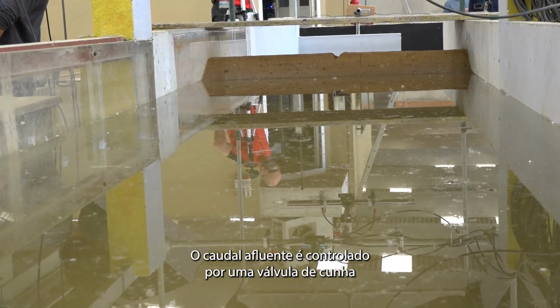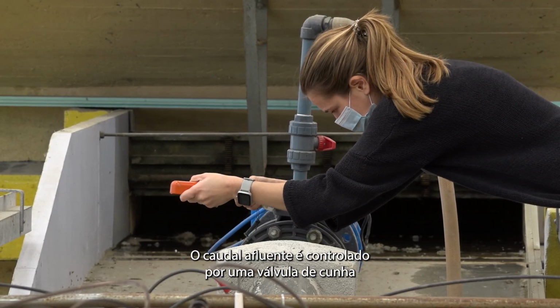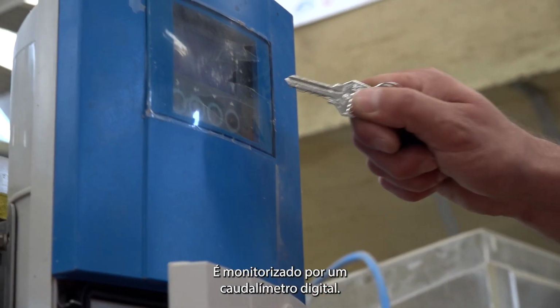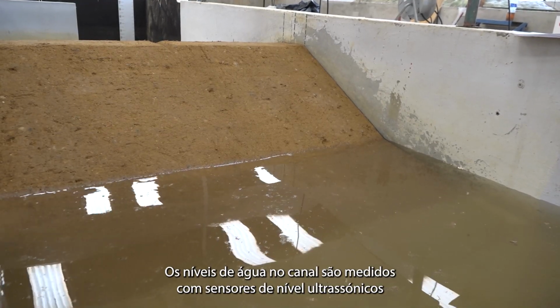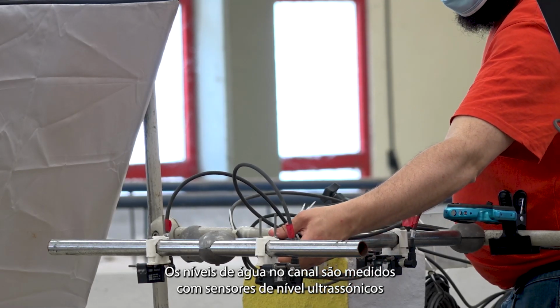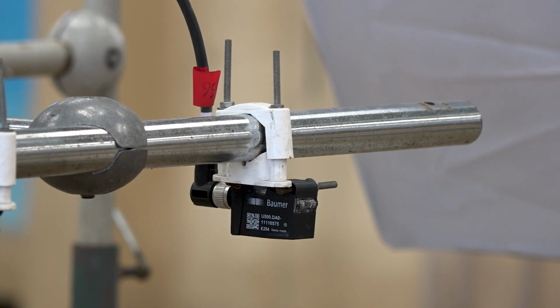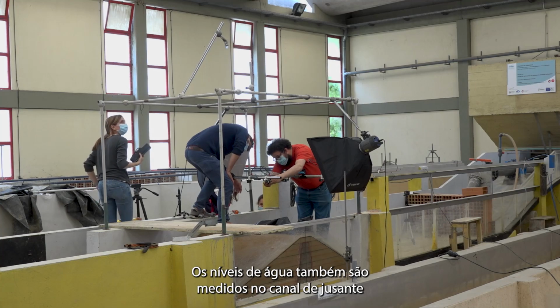The inflow discharge is controlled by a wedge gate valve placed at the entrance of the main channel. It is monitored with a digital flow meter. Water levels in the channel are monitored with ultrasonic level sensors placed upstream of the dam, some near the breach. Water levels are also measured in the downstream channel.